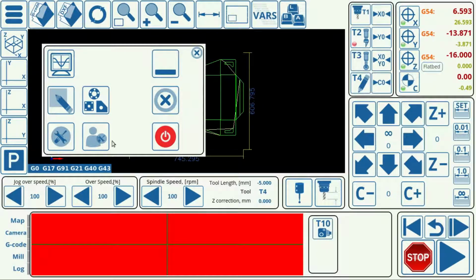Another note of interest is that it's not recommended to update your variables if you're updating the profile through the myCNC application, or to overwrite this CNC variables.xml file inside the profile folder if you're performing a manual update. The variables file contains your user settings, which would be reset to a default state should a user overwrite this file. So this is only recommended if a reset is necessary during your initial setup process.